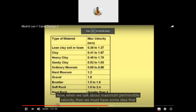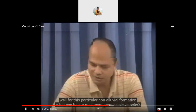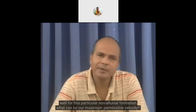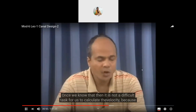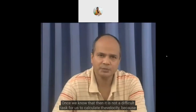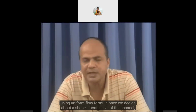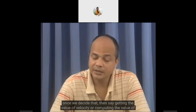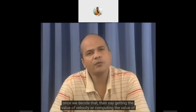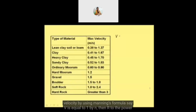When we talk about maximum permissible velocity, we must have some idea of what the maximum permissible velocity can be for a particular non-alluvial formation. Once we know that, it is not a difficult task to calculate the velocity. Using the uniform flow formula, once we decide the shape and size of the channel, we can compute the velocity using Manning's formula: v is equal to 1 by n, R to the power 2 by 3, S to the power half.